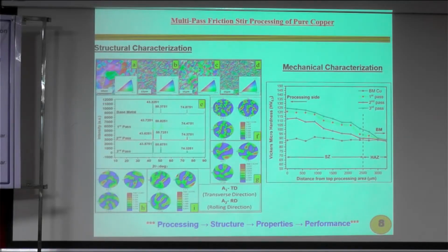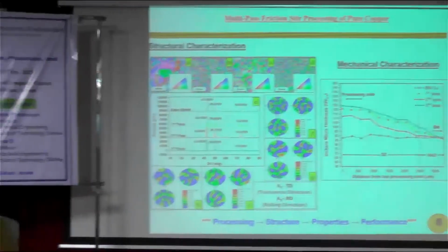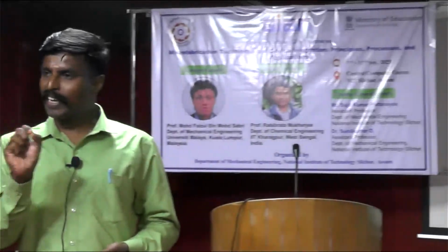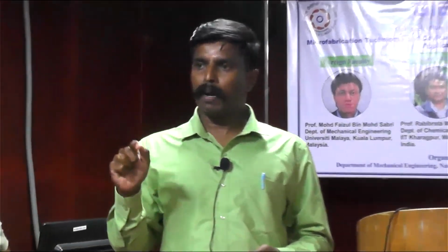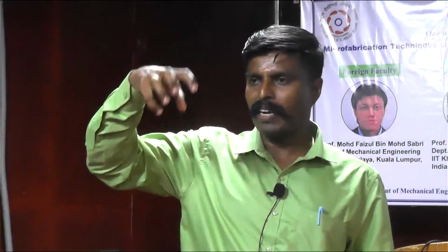Why are we keen on heat input? Because heat input is one of the parameters deciding the heat affected zone size. In all weldments, the weakest region is the heat affected zone only. The definition of the heat affected zone is the portion of the material adjacent to the welding region that is affected by welding heat. One factor is the thermal cycle, which is nothing but heat input deciding.